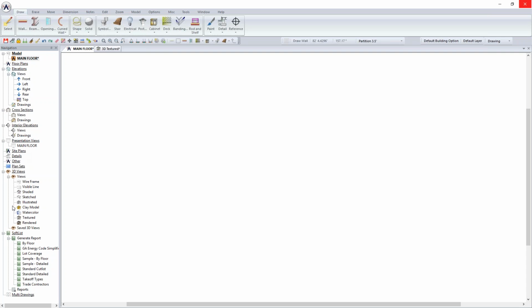All right, different various 3D views. Your soft list or bill of materials will all be generated from this. It basically gives you access to what do you want to see about the floor plan or the model that you're creating at this stage. You've drawn a wall, you want to see how many studs it takes, you go down to the soft list. You've got a building footprint, you want to see what the elevation looks like, come to the navigation menu, select the elevation. Okay, so this will give you access to all of that.